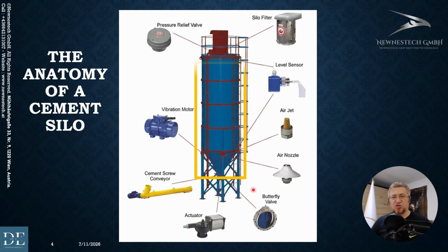The primary structure core is the main cylindrical container or shell. This shell terminates at the bottom in a 60-degree conical hopper, an optimized angle designed to facilitate the smooth gravity extraction of stored cement powder. At the top, we have a roof deck with a gentle 5-degree slope, engineered to drain rainwater or melting snow toward the outer rims and away from the critical equipment.